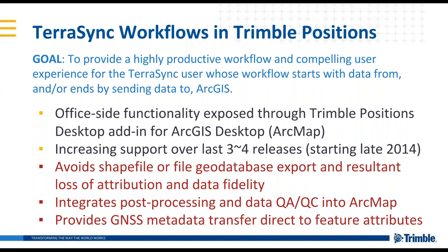The post-processing environment and the QA/QC is then also done within ArcMap. So you'll see in one of my demos that in this dockable window that sits inside ArcMap, you have the ability to do the post-processing, to dive in and look at the properties of the session, and to look at the details of the features and geometries and all that kind of stuff. We also provide GNSS metadata transfer direct to feature attributes.